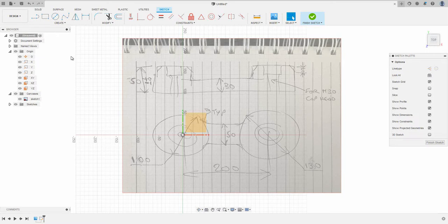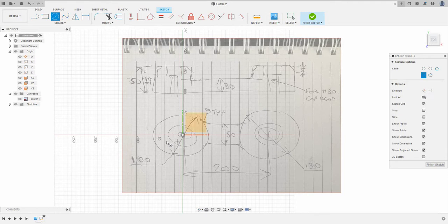I'm going to create some circles, so let's go to the circle command, left click on it. I'm going to select on the origin button. If you hover over the origin on the screen, you'll see a little blue square appears. Just left click on that. That's now snapping to the origin on my sketch, and as I move my mouse you can see it's rubber banding a circle, and there's a blue highlighted text in a box which is indicating the diameter.